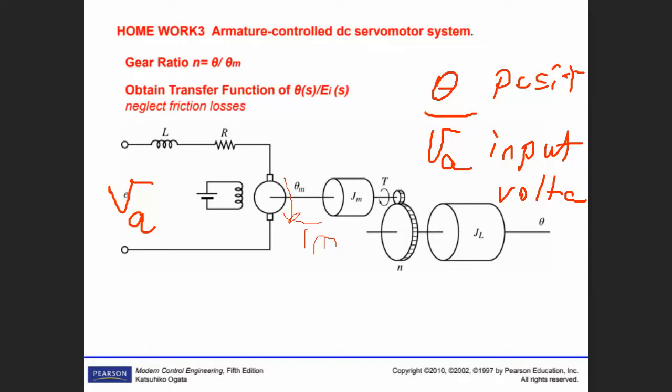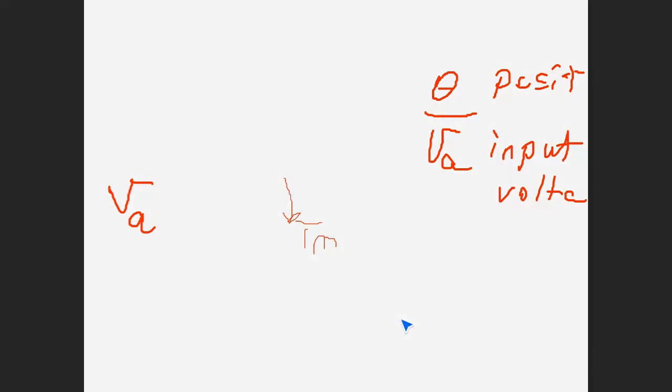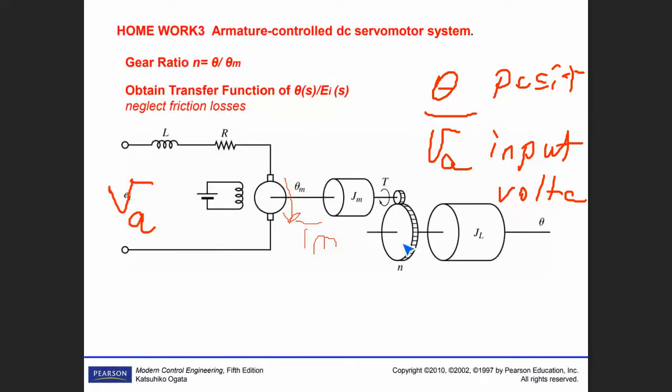In an electric vehicle, of course, you have a battery plus a power electronic device to control the electric machine, to control this voltage or frequency as well, and then the electric machine model produces torque. There is only one gear, which is approximately a 1 to 10 ratio, so the speed is reduced to 1/10.